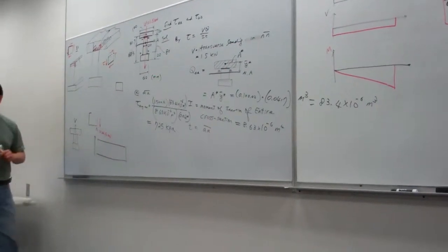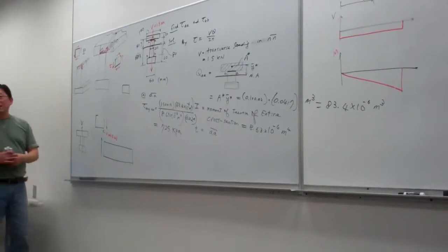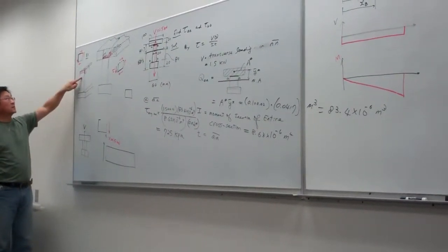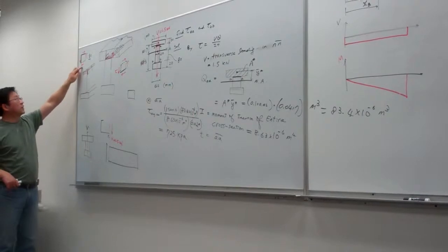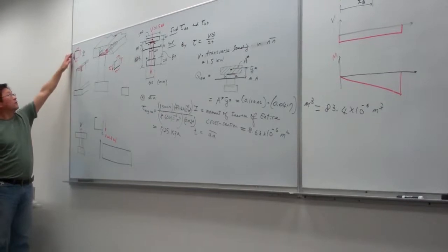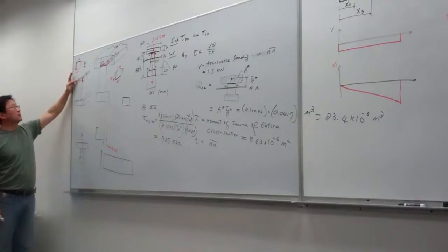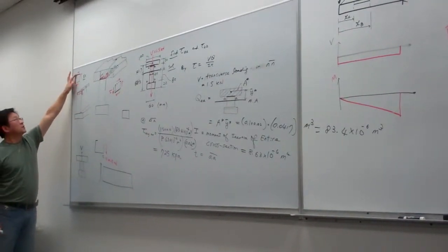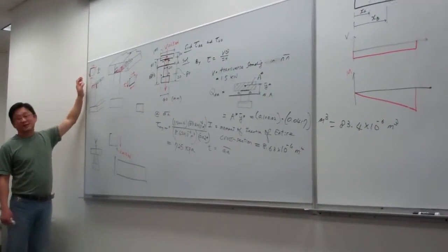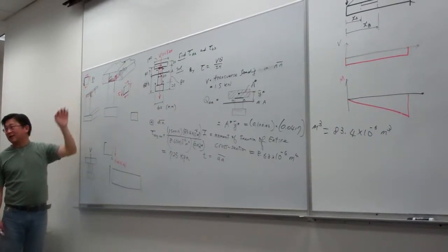So the 725 kPa is going along the top. Is that the shearing at the top, or is that the vertical? For this case, basically the magnitude of the force is 725. Okay, and then for this case, this is a shear stress acting on this plane. This is a shear stress acting on that plane, and both are not the same quantity. They are not the same entity. Okay, again, the shear stress.